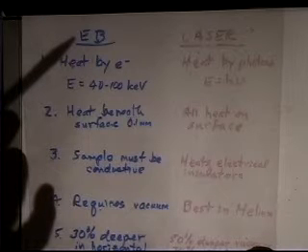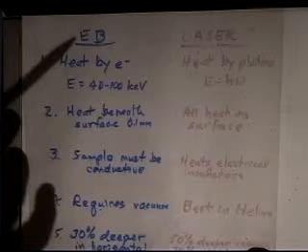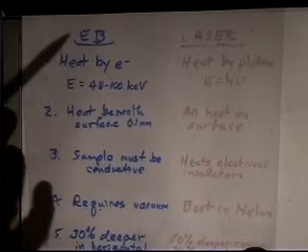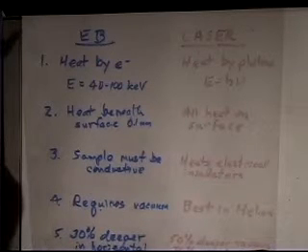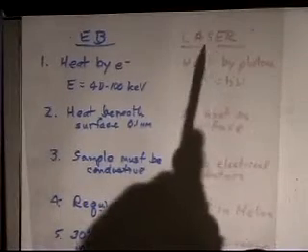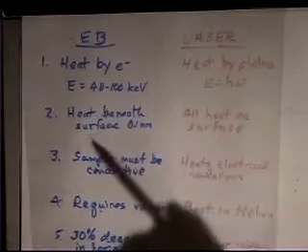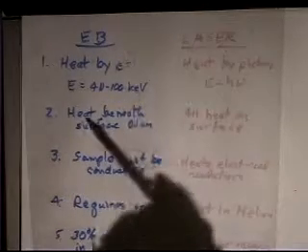You're blowing the surface apart. You actually create micro explosions on the surface, which cause chunks of material to peel off. So those very high power densities are not very useful for welding, but you can reach them with these technologies, although it gets kind of pricey.